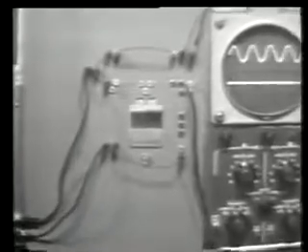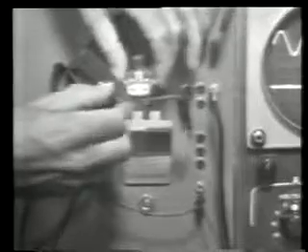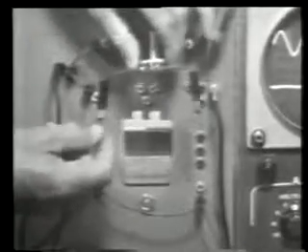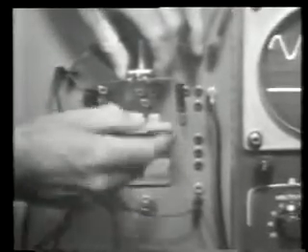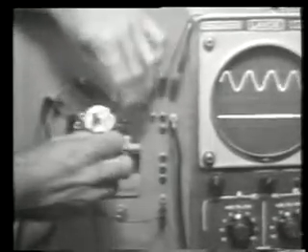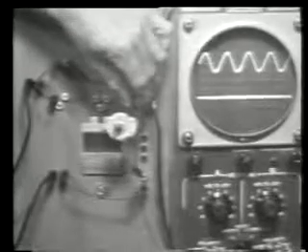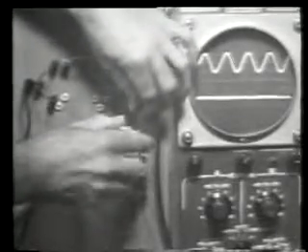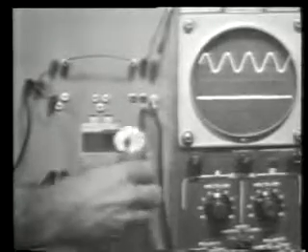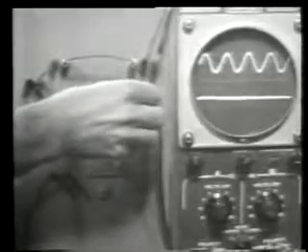To show how a simple voltage divider can provide filtering, we'll use two variable resistors, just like this one. Now you'll note that this is nothing more than a variable resistor that I've connected with a couple of test leads so that I can plug it directly into my trainer for use during the demonstration. Now we'll put one here in the series position and one here in the shunt position to illustrate how the voltage dividing principle will work to affect the output voltage. Well, here, I'll just plug this one in, the shunt position, like that, and there, and we'll put this one in the series position,